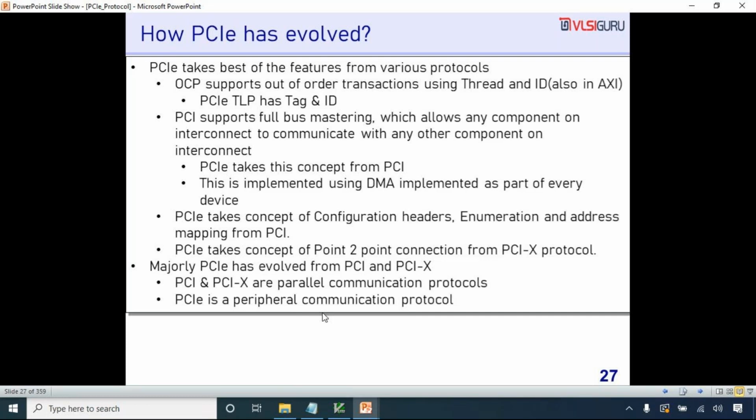So you mentioned the presence of clocks makes it a parallel protocol. No, one of the aspects of a parallel protocol is that the clock is always there, because even serial protocols like I2C have a clock. The speed of transfer is very low, let's say 10 megahertz, so skew won't be a problem at all. Here also we have multiple devices, the same devices. But at any given point of time, we can communicate to only one device, right? So why is the load coming here? Because it comes only when multiple devices are being communicated with. See, even though you're doing a transfer to one device, the other devices' load does add up to that, right? The signal may need to be transmitted.